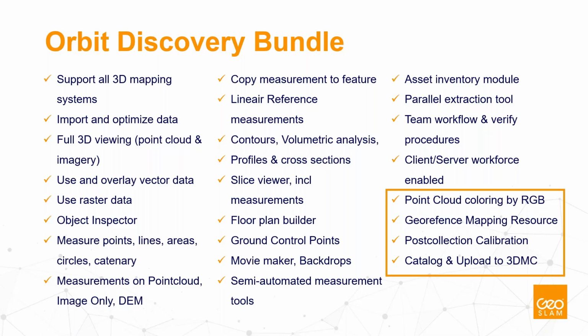We do a very specific calibration to begin with, that's then going to allow you to clip and unclip your Horizon without the need to regularly calibrate it whilst you're capturing data. But we also want to empower our customers so that if they did unscrew the camera or felt there was a bit of a misalignment in the data, we'll show you how to do a calibration utilising Orbit, and we can make sure that you're having the high quality data that you're looking for.